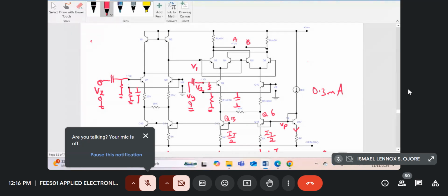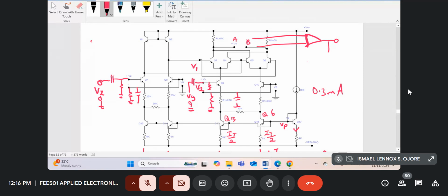And then the outputs, these two outputs, come to your difference amplifier, and the output V naught is with respect to the other. So for this circuit over here, all the signals have got a common reference. So if you got a scope input, the grounds are all common. So this probe can go here. This probe can go anywhere. This other channel can go anywhere. You can either put it at point A, you can put it at point B. You can connect this to either point A, you can connect to either point B. There won't be any problem at all.